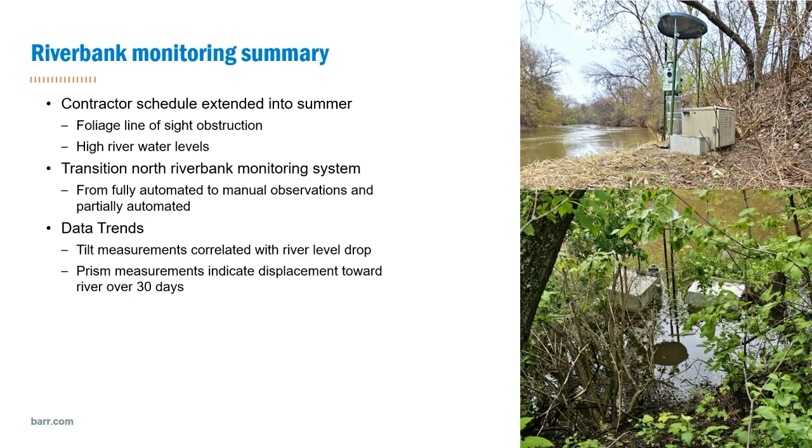The riverbank monitoring program, since the contractor's schedule really extended into the summer, as I said, we had some issues. There really wasn't a good place to put the monitoring equipment, so we mounted the total stations on the south riverbank of the project site, and set them up to run. But as time went on, the foliage came out, and we had some high river levels that actually flooded out one of the total stations.